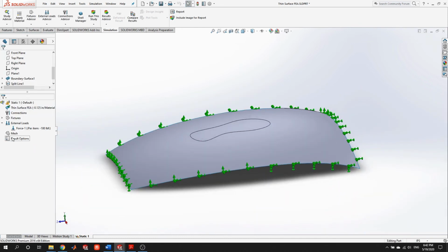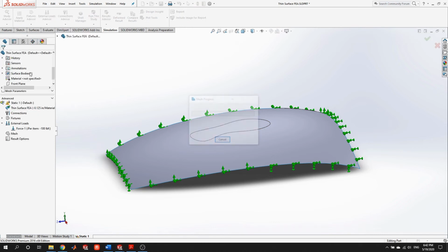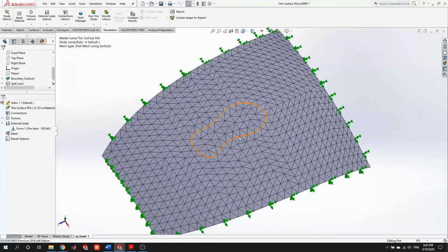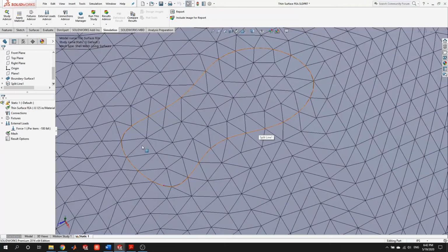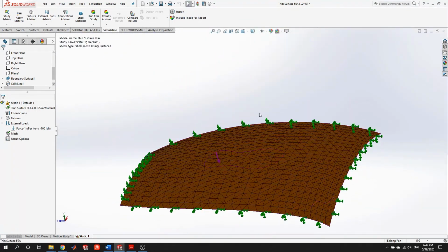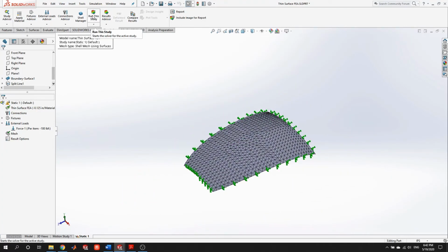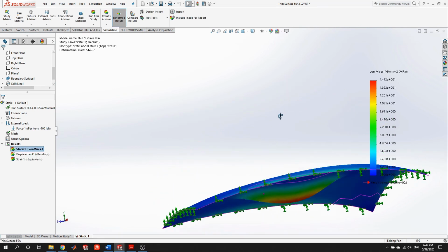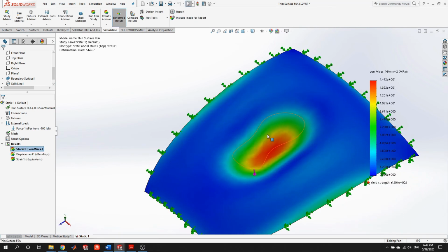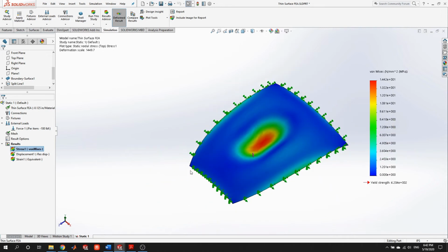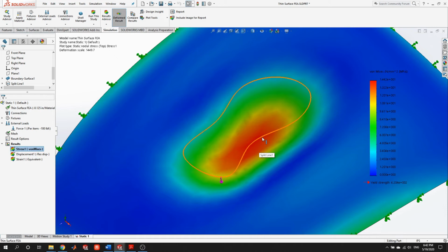Okay, now we're going to go back to the mesh, create the mesh. We can leave this at default right now. All right, we look around the area, we see if there's any unusually shaped elements. Everything looks good. All right, so now let's run the simulation. And this is good because you can see that it has now locally deformed, and we want to look for maybe the boundary conditions being stressed a little bit, but certainly kind of a smooth transition of the load outwards.